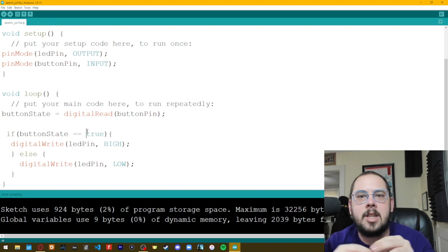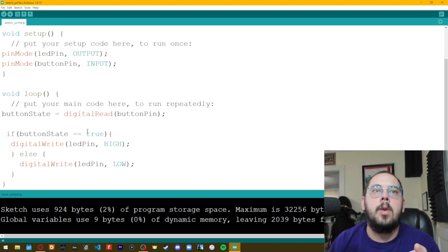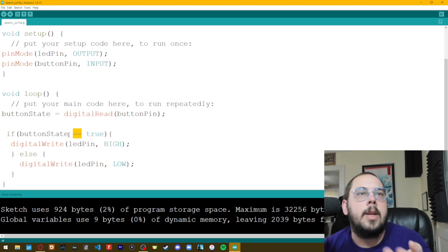And basically that just gets into more things like data types and stuff like that. But the short version is I find Arduino works best with 2 equal signs here in the conditional statement. Sometimes you may want 3. It's more on a case-by-case basis, but for what we're doing and what the students do, 2 tends to work best in the conditional statements.